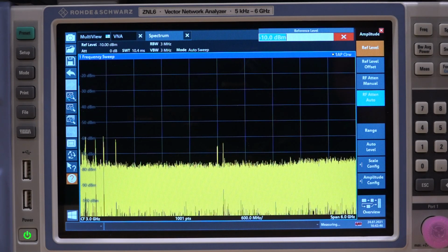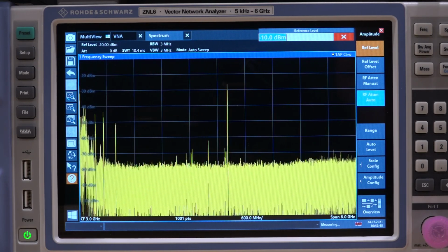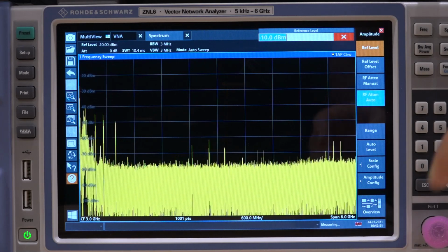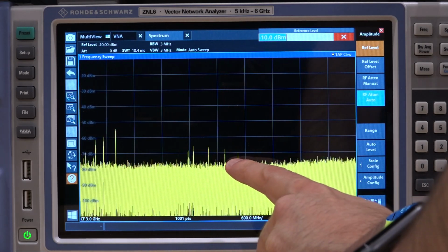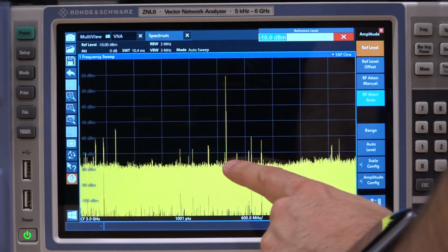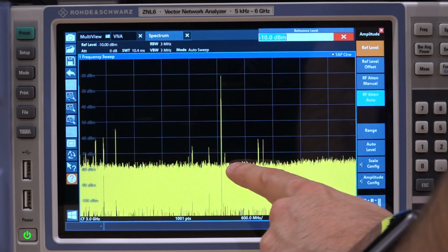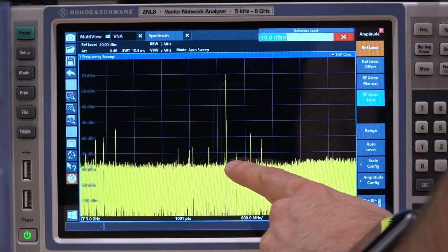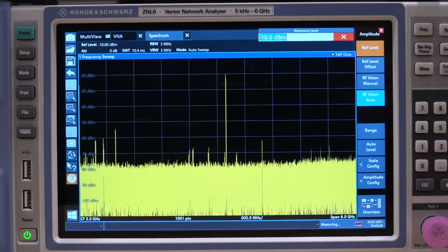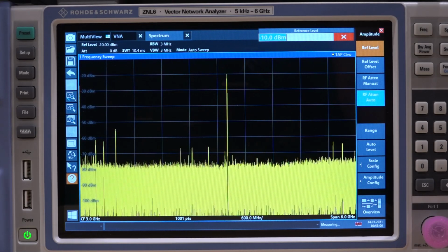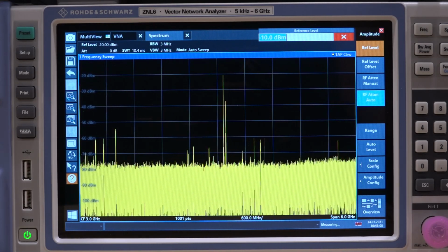All right, here we go. So here's our signal. Let me get the ground. There it is. Look at that. That's exactly what we see. This is a 3 gigahertz signal on a 6 gigahertz span, so it's in the middle, roughly around 3 gigahertz. And indeed, we have a signal jumping all over the place as the PLL tries to lock, and it's within the frequency specification of this IC, about 3 to 3.4 gigahertz or so. That's great. I think the VCO is working.